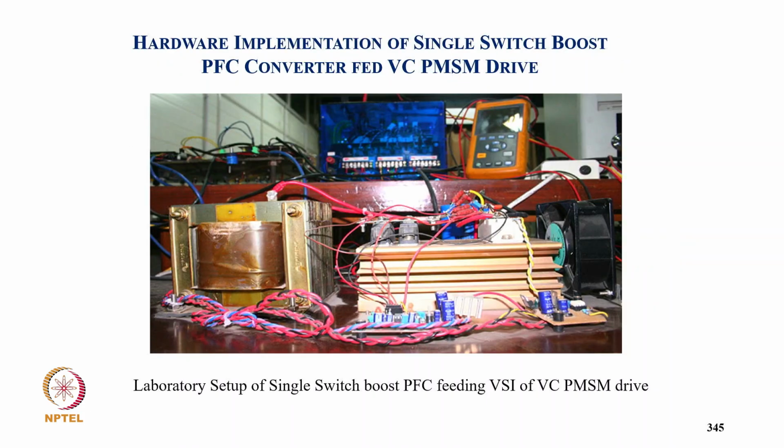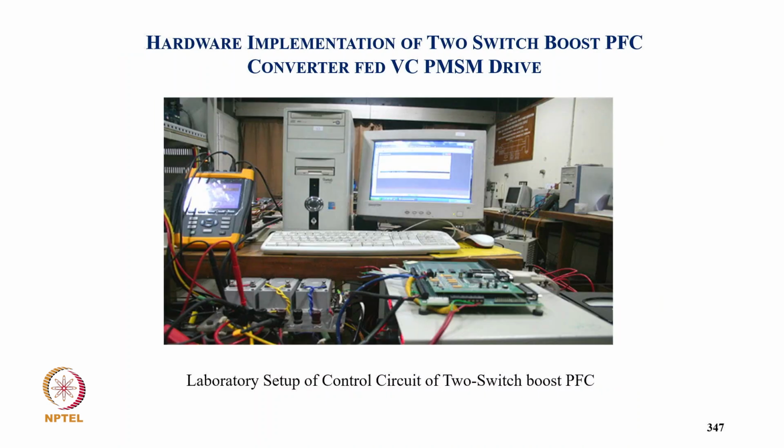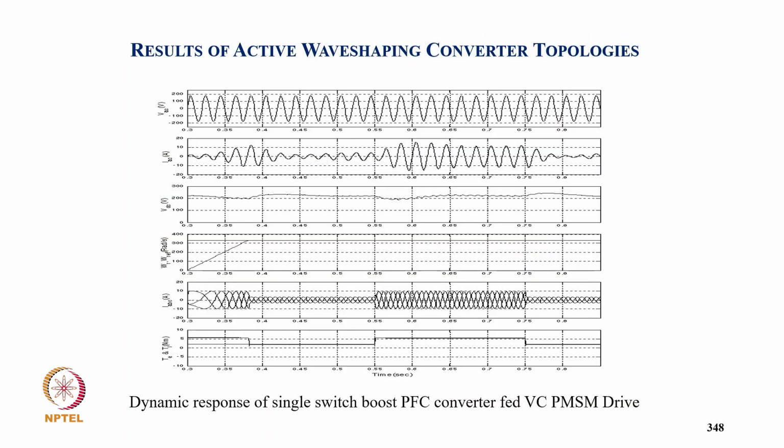And this is typically the hardware implementation of a single switch PFC converter fed vector controlled induction motor drive. And this is the laboratory power circuit of the two switch boost converter, and the laboratory set of the control circuit of the two switch boost converter, and these are the simulated results of the dynamic response with the single switch boost converter. So you can see the supply current during starting, then load application and removal, how the supply current is in phase with the supply voltage and remains sinusoidal.